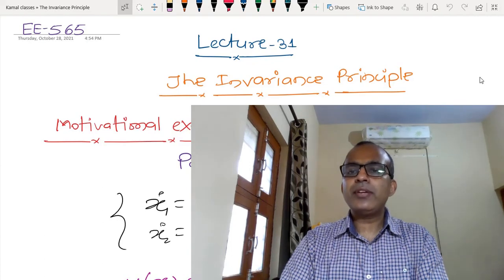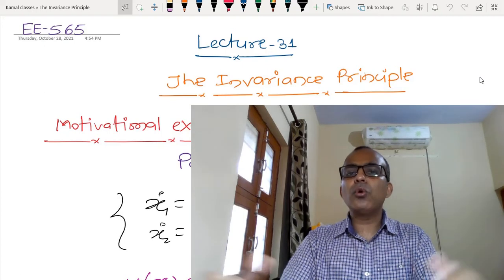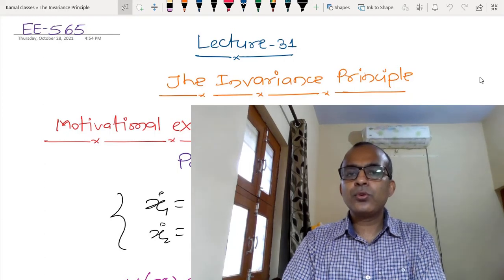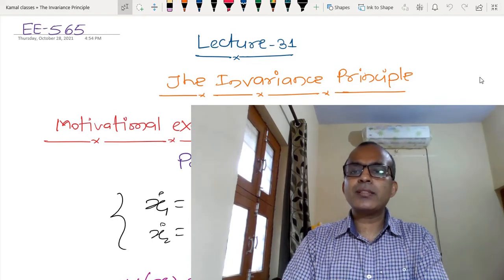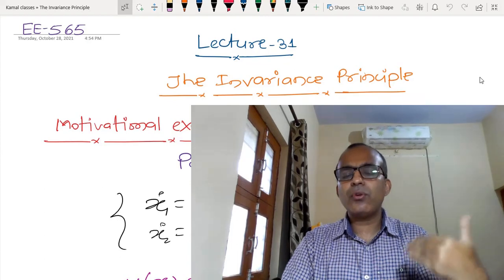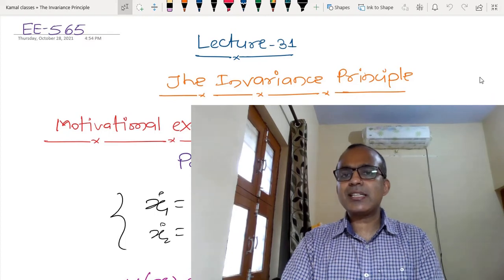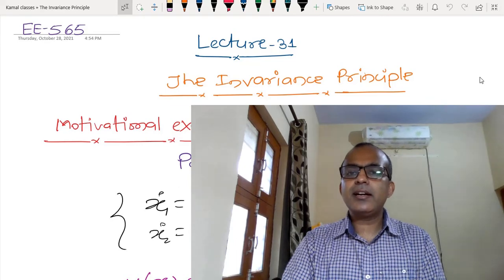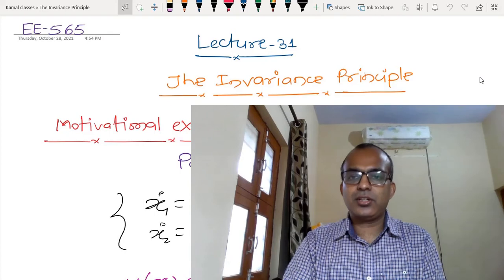So what we have to do is change the Lyapunov function, or add some more ideas, or do further investigation to tell whether, using that particular Lyapunov function, my equilibrium point is stable or asymptotically stable, or we have to completely develop a new kind of Lyapunov function. In the previous class, we found that using the variable gradient method, one can develop a Lyapunov function at least for a second order or third order system.